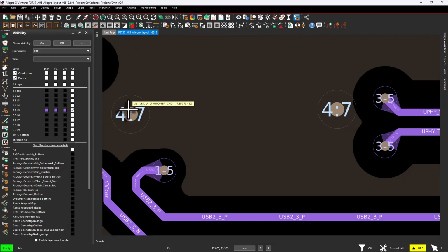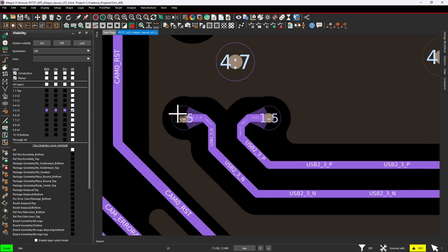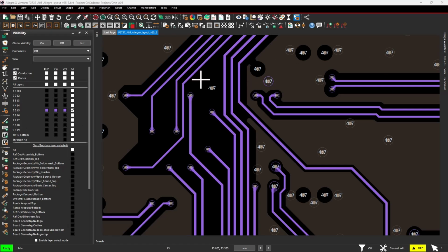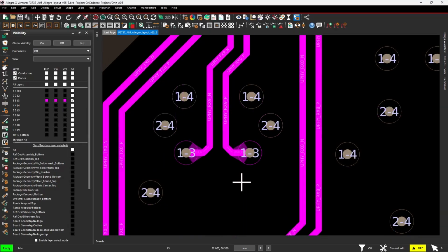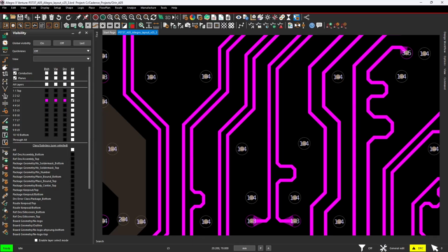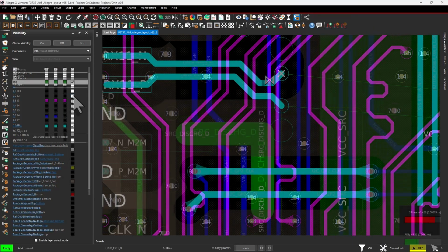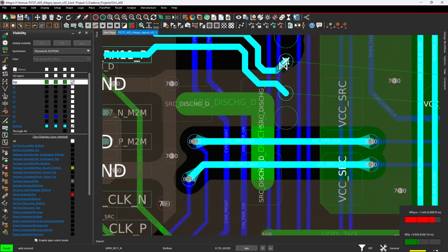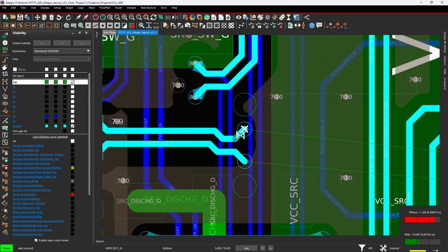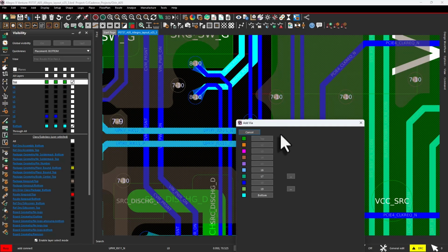So what's the fix? The fix is to keep your differential pair vias symmetric. Keep the same anti-pad geometry, maybe even combine them if possible. Use equidistant spacing and have your ground return vias placed at the same angles on both sides of the pair. This keeps the electromagnetic field equally coupled across both legs of the diff pair. If you're using Allegro X PCB layout, via symmetry is built into the routing tools already. So you don't have to calculate return path via spacing manually. It does it automatically.